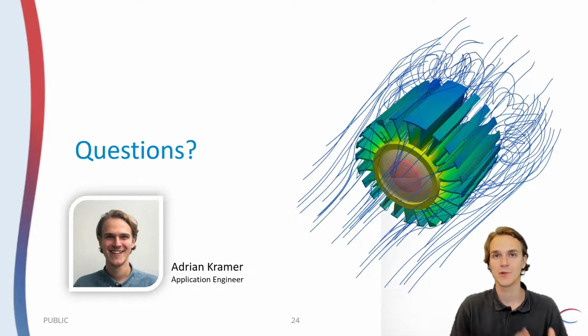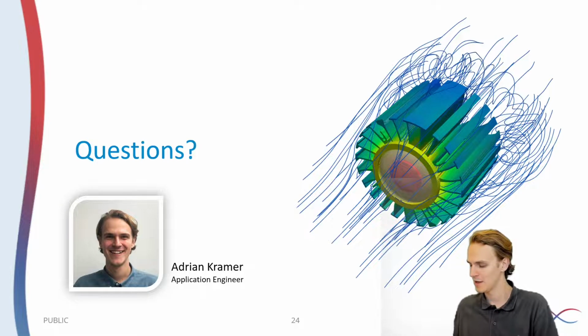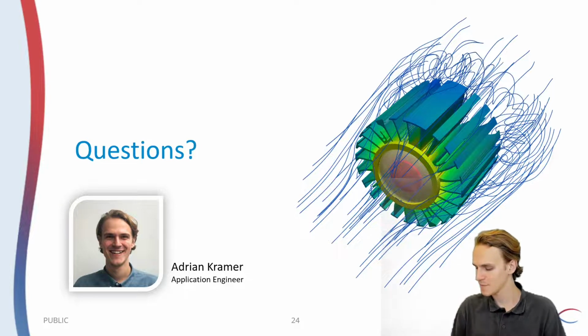In the example that I gave, I implemented pressure inlets. For a forced convection case setup, you can either use a fixed flow rate inlet or a fan inlet. And so you can actually model your specific fans directly in ColdStream, and those will also be part of your library. That is readily available right now on ColdStream.